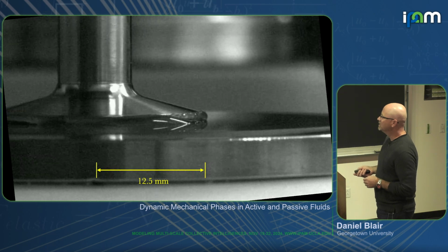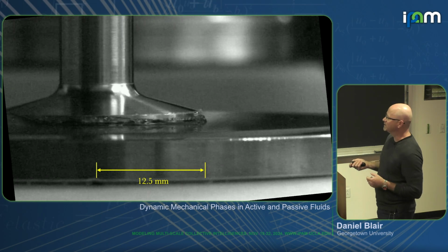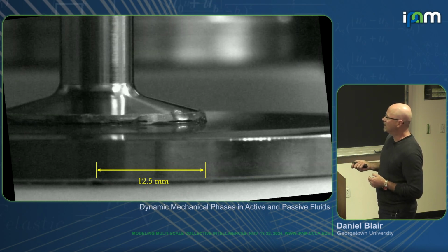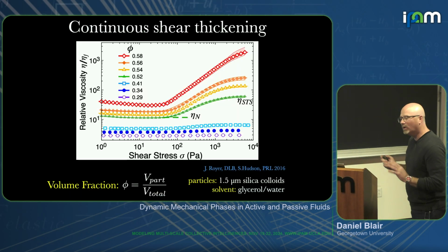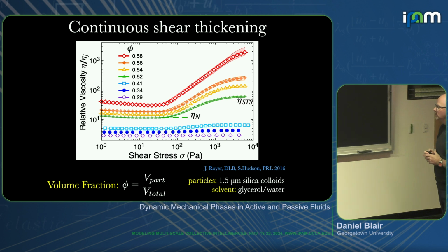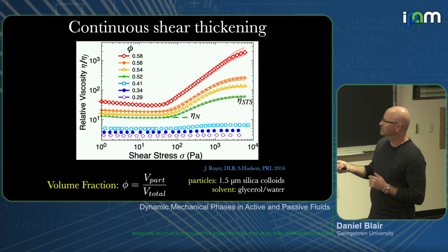You can see it. That's just a colloidal suspension being sheared. There's a lot of shear at the edge, so it kind of wants to shear a lot. It solidifies, pops out. All right, so what does that look like as a graph? Well, here's your viscosity, the viscosity of the thing I'm measuring divided by the background fluid, so water. And so, as you can see, if I have a very, very low concentration of those particles, this is like your toothpaste, it's going to act a bit like a Newtonian fluid, may even thin a little bit.